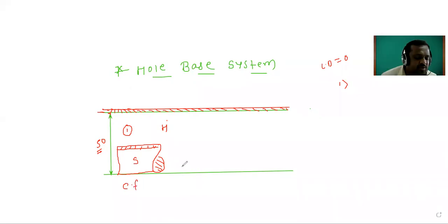Okay. Then how to achieve the interference fit? If we have to achieve the interference fit, again we have to manufacture the big shaft because we have the fixed size of hole. Because we have the fixed size of the hole, and suppose we have to achieve the interference fit, in that condition we have to manufacture the shaft with big size like this. So this is the tolerance for the shaft. So this is our shaft.